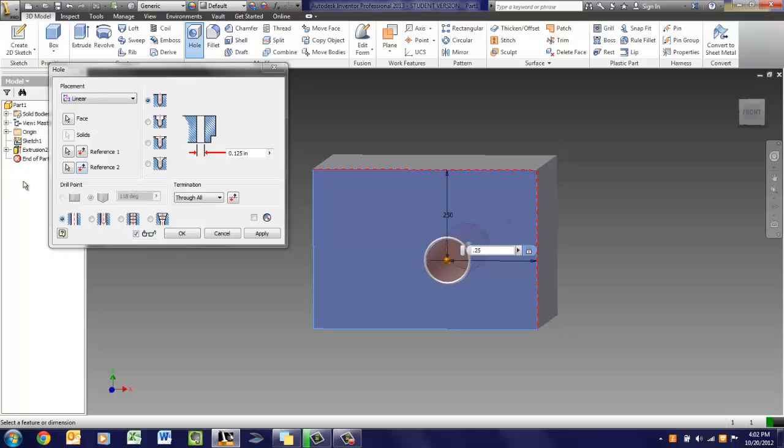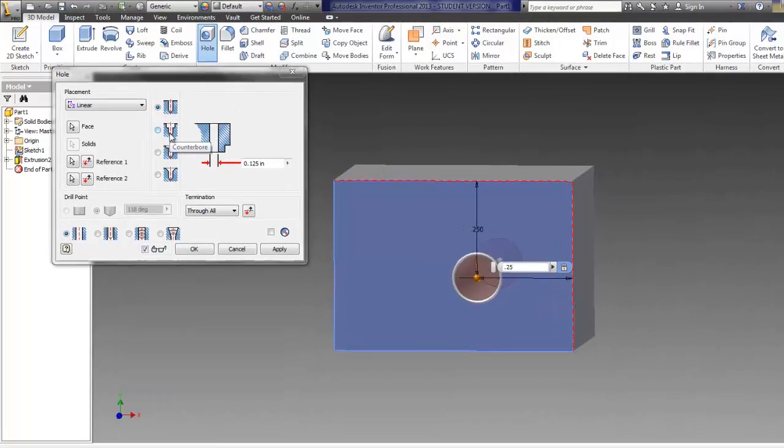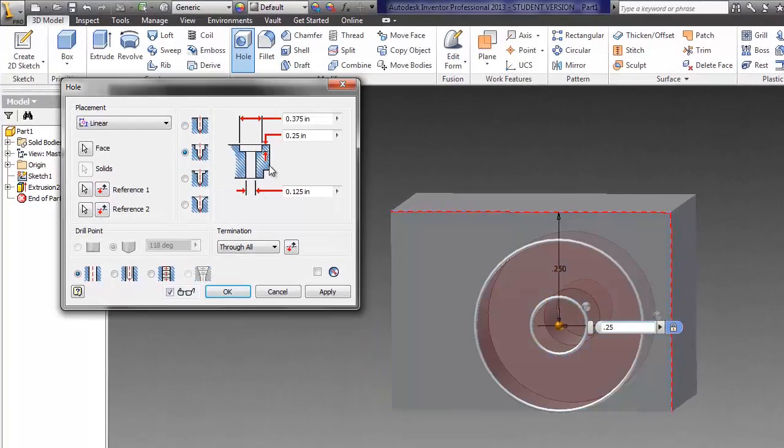Now I also have some other options. Besides the placement options, we also have the option of types of preparation. Right now, as you can see here, it is drilled. We can also do a counterbore, which is going to give us a large hole. Generally it would be used in manufacturing for placement of a bolt head. Okay, so it's recessed and below, so that it's flush with the surface.